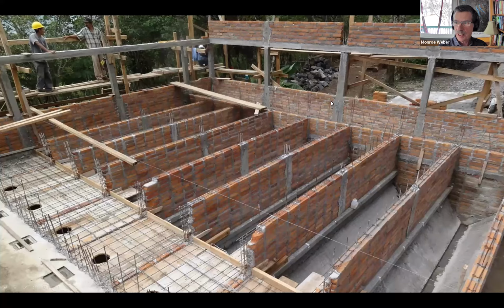Brick walls out here look conventional. The bricks are like this. Do you see that difference? Walls that have to hold back water, the bricks are on top of each other so they can run rebar in them. Walls that are just building walls have bricks overlapping and they're not reinforced. See, if I hadn't pointed that out, you might not have even noticed that those bricks were different, right?